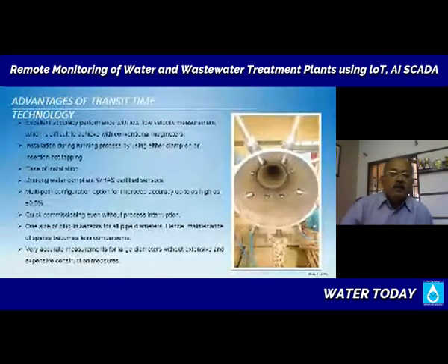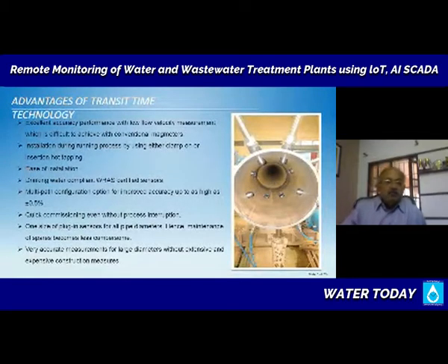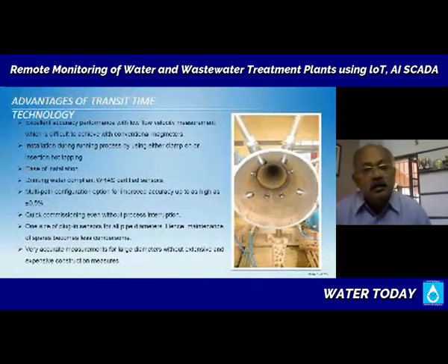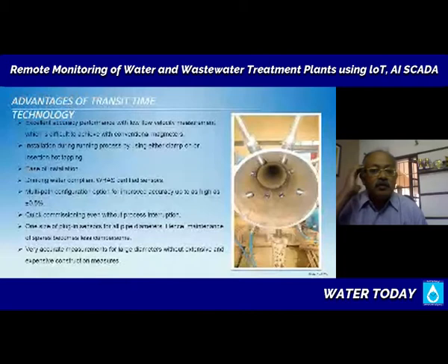In Mumbai, we are having pipes. The largest one is 3 meters diameter that brings in water to the city. So you have to measure the velocity in a 3 meter diameter. That's a huge pipe. The biggest that we have done in India is 6 meter diameter pipe. That is at the inlet to a hydroelectric power station in a penstock. So the technology, why I mentioned 6 meters.